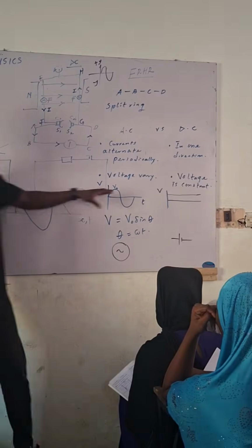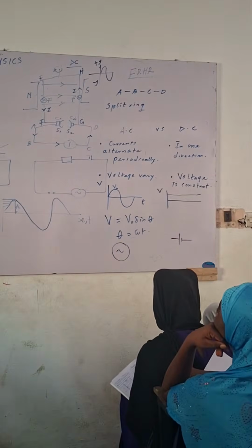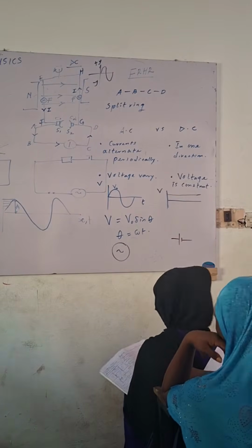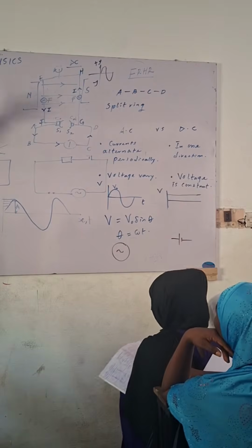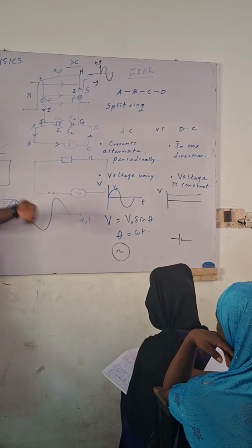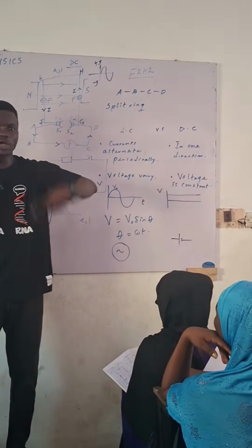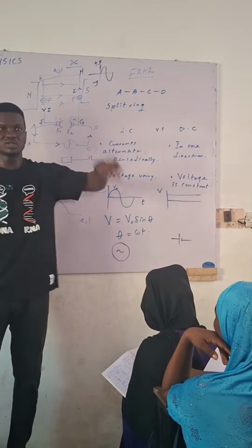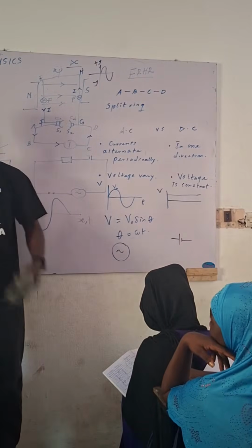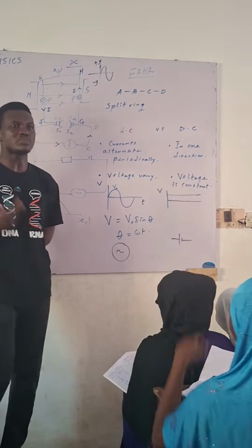As it generates voltage, the voltage you have generated, we used a generator. So the question they can ask you here, number one, is: what does your generator do? It converts mechanical energy to electrical energy. How does it? By rotation of a coil in a magnetic field. And if you want to determine the direction of the current, how do you determine it? You use Fleming's right-hand rule.